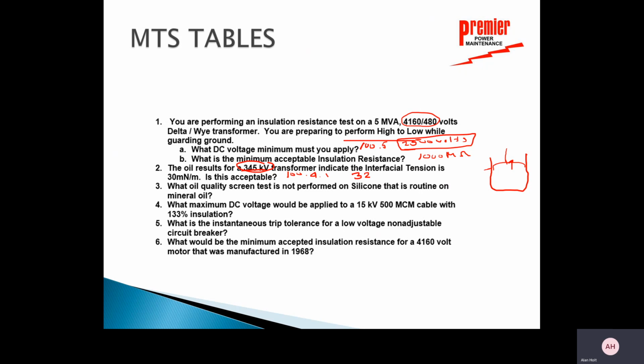Number 3, what oil quality screen test is not performed on silicone that is routine on mineral oil? Well, that's the interfacial tension test. You do not run interfacial tension on silicone. What maximum DC voltage would be applied to a 15 kV 500 MCM cable with 133% insulation?